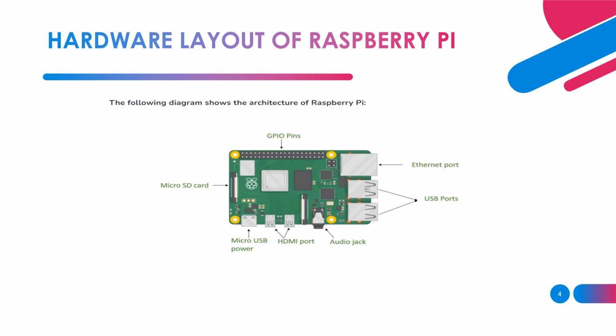General purpose input-output pins are generic pins on an integrated circuit. A GPIO is an input or output pin which can be controlled by the user at runtime. GPIO pins can be configured to be input or output. Input values are readable, normally high equal to 1, low equal to 0. Output values are writable. Input values can frequently be used as interrupt requests.